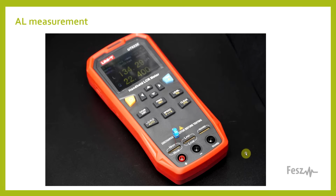First, to get an idea of the AL value of the cores, I used an RLC meter. While you could measure at any frequency, the general recommendation is to measure with a low frequency, but still have a good measurement resolution. The higher the permeability of the material, the lower the test frequency should be.